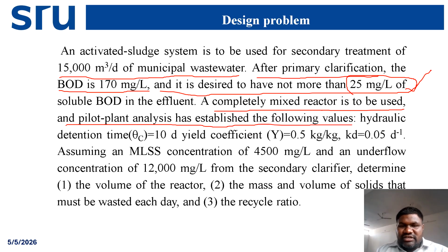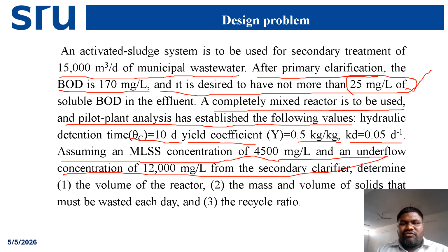Hydraulic retention time, that is theta C, is given as 10 days, yield coefficient Y equals 0.5 kg per kg, and the decay constant Kd is given as 0.05 per day. Next, assume an MLSS concentration of 4500 milligram per liter and an underflow concentration of 12,000, where MLSS concentration means X equals 4500 milligram per liter.